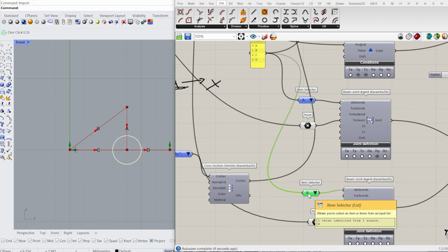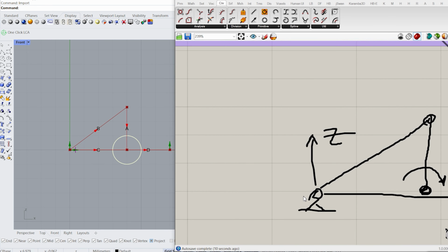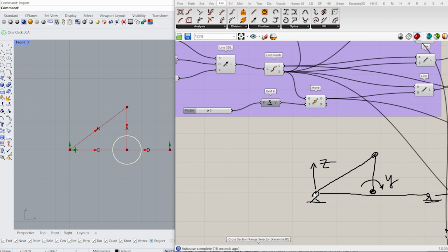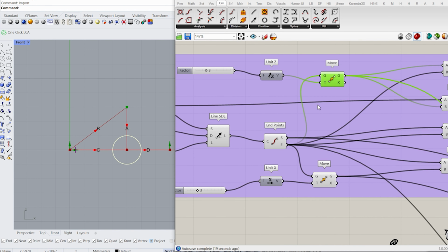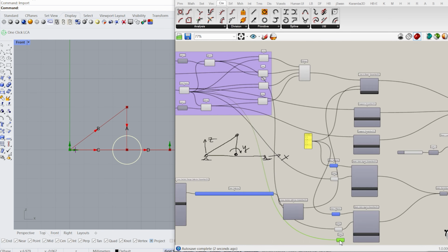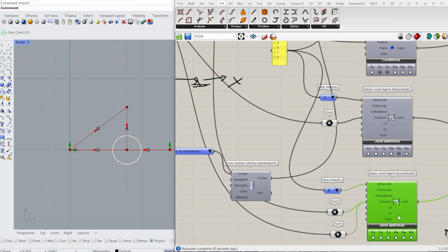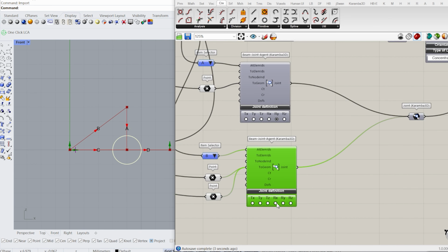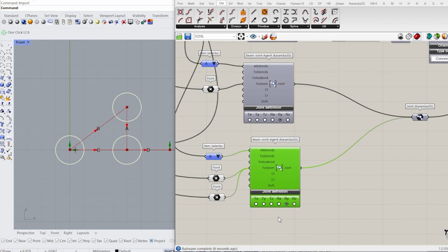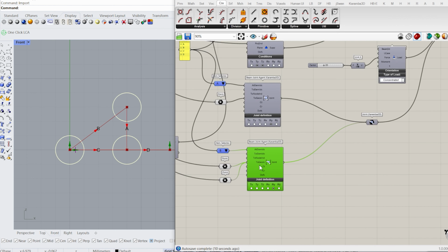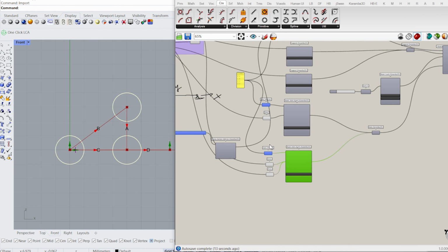And not only here, but this element also needs a hinge here at the very beginning, because it has to know how it is connected to this point, to this node. So here I'm going to need this first point. Here I'm releasing also the y direction. Yes, now I have the joints.